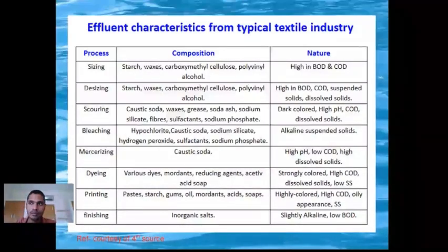And the tertiary treatment plant is mostly designed as per the requirement of the output. If the water is being funneled for domestic water use, then disinfection is done so as to remove pathogenic bacterial contamination. If it's being released into nature or freshwater bodies, then the nitrate levels are considered. Even within the nitrate level, they make sure that it's not too high, so denitrification lagoons are used.